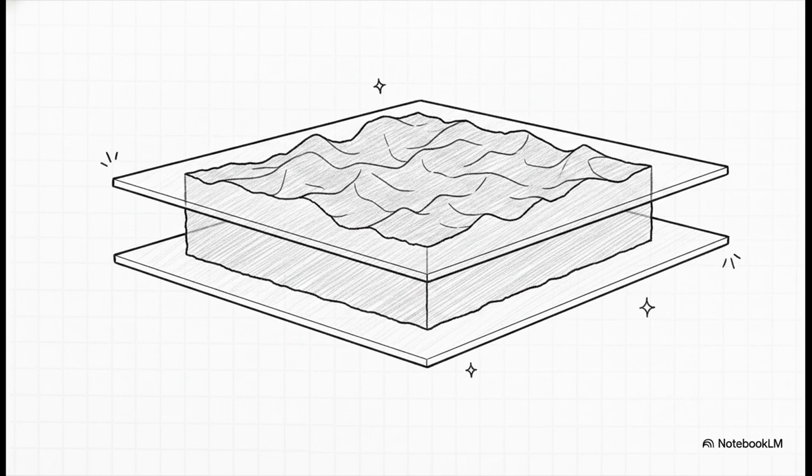We're upgrading from evaluating a 2D line to an entire 3D surface. Flatness simply takes that 2D straightness concept and sweeps it across a full area. The standard tells us that flatness requires all points of a surface to lie within a tolerance zone bounded by two parallel planes. So, instead of two parallel lines, imagine trapping your entire part's surface between two perfectly flat parallel sheets of glass. If any point on that entire surface bows up or warps down enough to break through the glass, the part is scrapped.